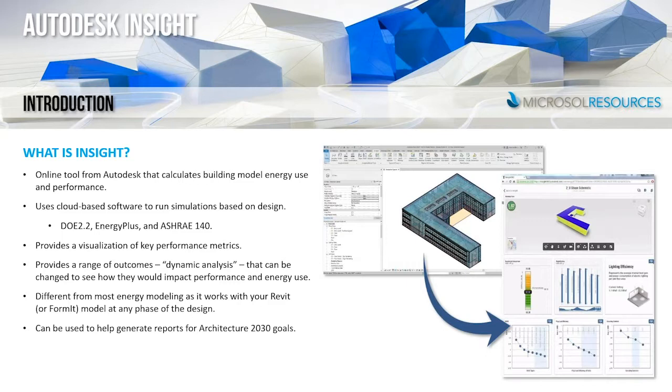As some of you may not yet be familiar, the first question is, what is Insight? It is an online tool from Autodesk that calculates building model energy use and performance, and it's accessed through the Analyze tab in Revit. Under the Analyze tab, over on the far right, is where we would find our information to be able to use Insight. Insight uses cloud-based software to run the simulations based on design. DOE 2.2, EnergyPlus, and ASHRAE 140 are the main simulation engine platforms used, and the simulation engines are validated and updated frequently to meet the standards of those tests.